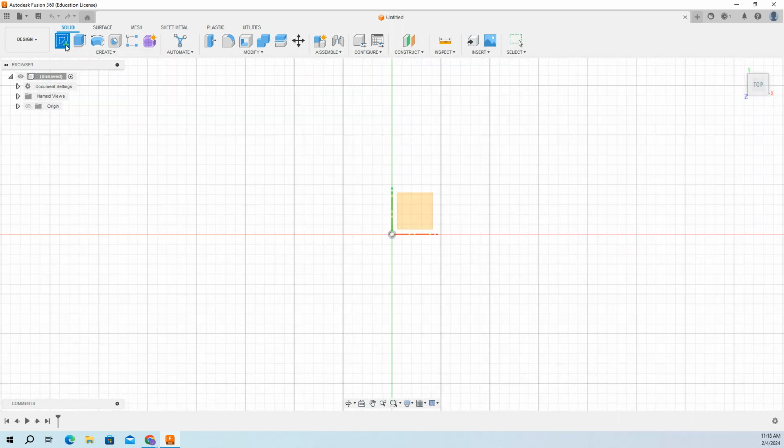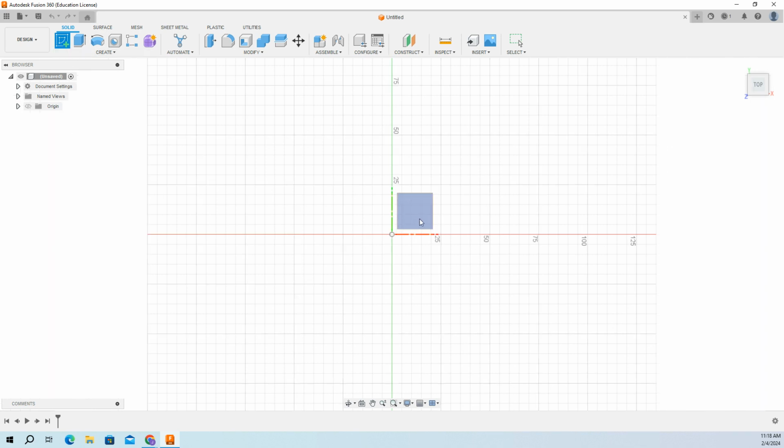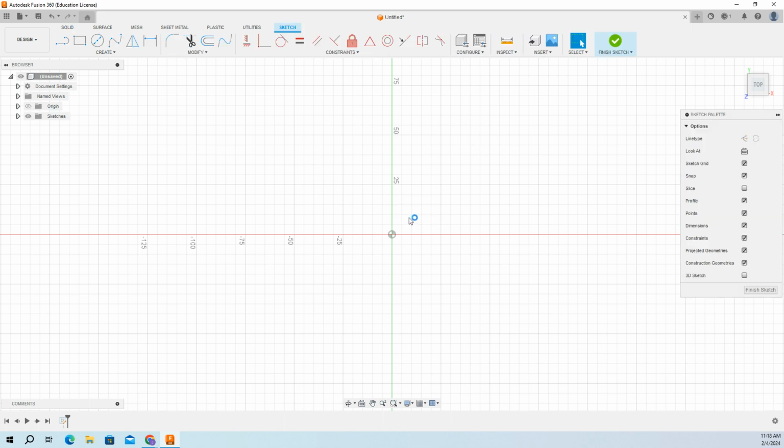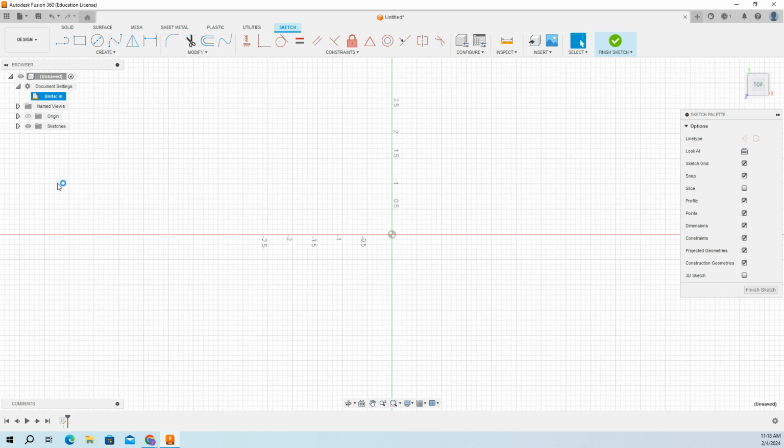So right, I hit plus, then it asks me which plane I want to design on. So I picked the front plane. Now I'm in a sketch, right? I'm gonna go to my document settings, drop down. I'll change these to inches. I'm not gonna set as default because we do a lot of millimeter stuff.